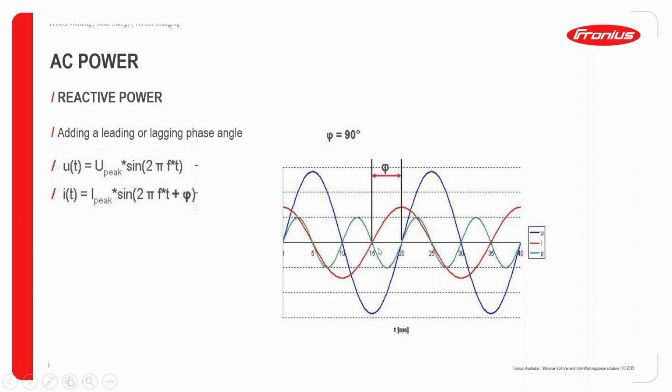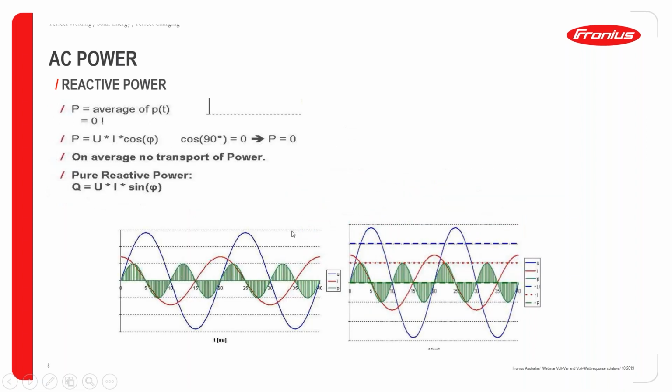Because now if we would like to calculate the power, and power is always V times I, as you can see, this is the power waveform, which is the V times I. And if we really want to take the RMS value of the power, then we have to take the average of these instantaneous power values.